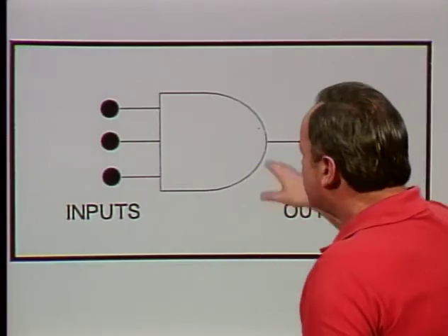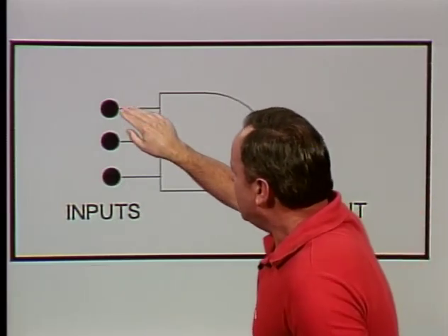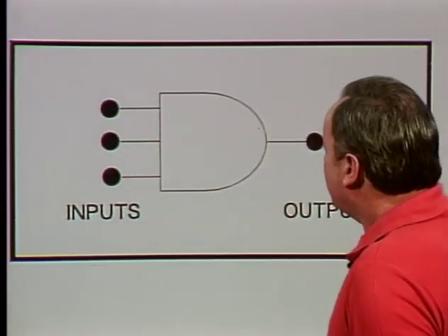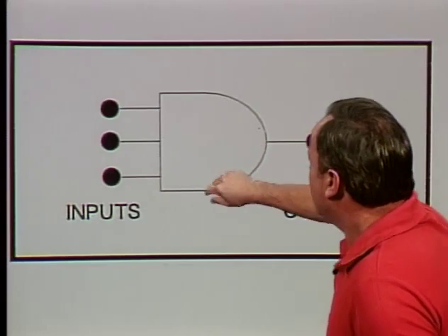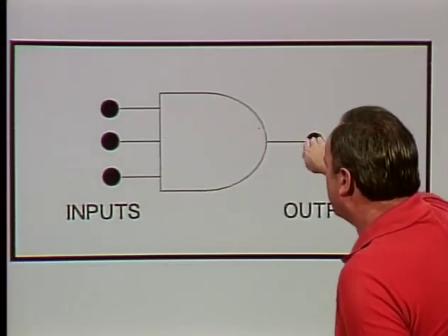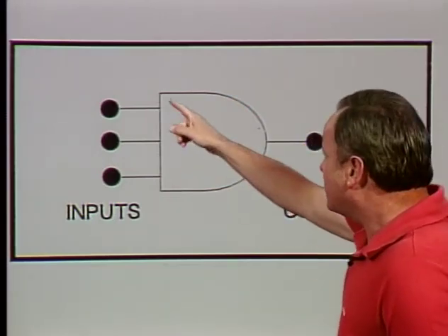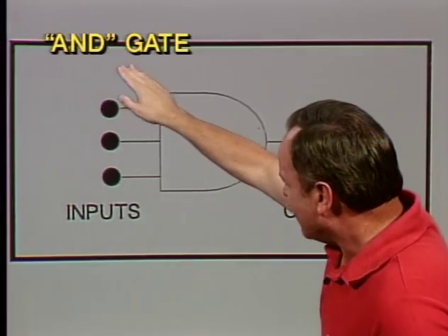And this is a logic gate, and here's the way it would work. First of all, you have an input, and each input can have either a charge on it or no charge on it. And if a certain condition satisfies the requirements of the circuit, then information can be passed out here. If this is true, then I'm going to turn the charge on here and put an output here. This particular logic gate we're showing right here is what is known as an AND gate.